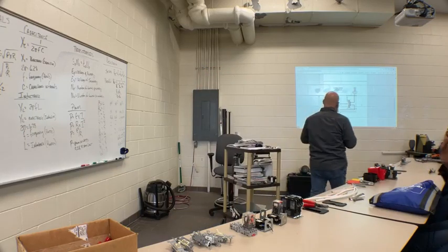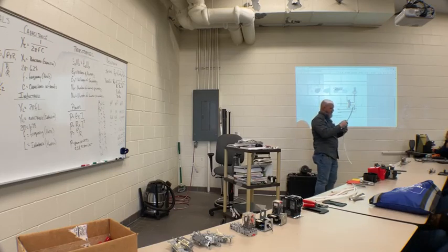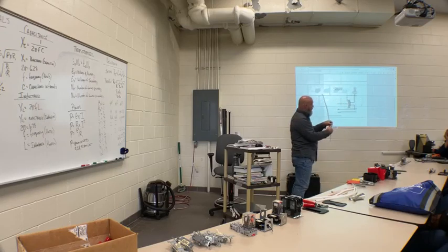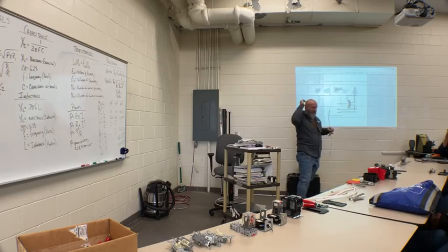This is the power coming in, this is the power going out, and your lights are wired up together. So this would be going to your light, and this would be your power coming in. And then this switch is breaking this hot circuit right here to cut the light off.